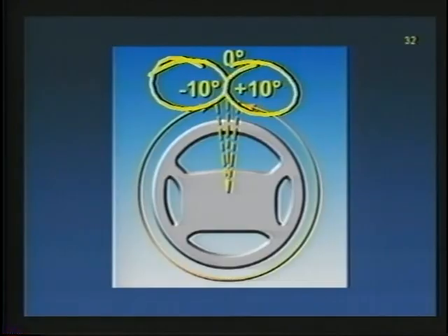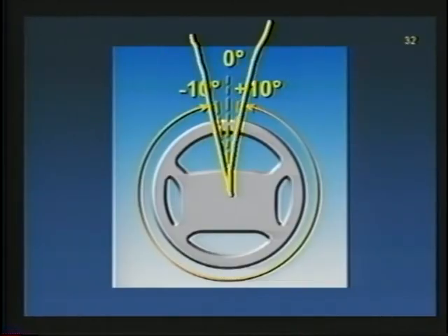They're 10 degrees either side of center. Remember when Mike was talking to us about that marker pulse? Well, this is where it comes into play. Before the system is going to allow us to lock into the next mode, we have to pass through 10 degrees either side of center, just right inside that V, if you will.